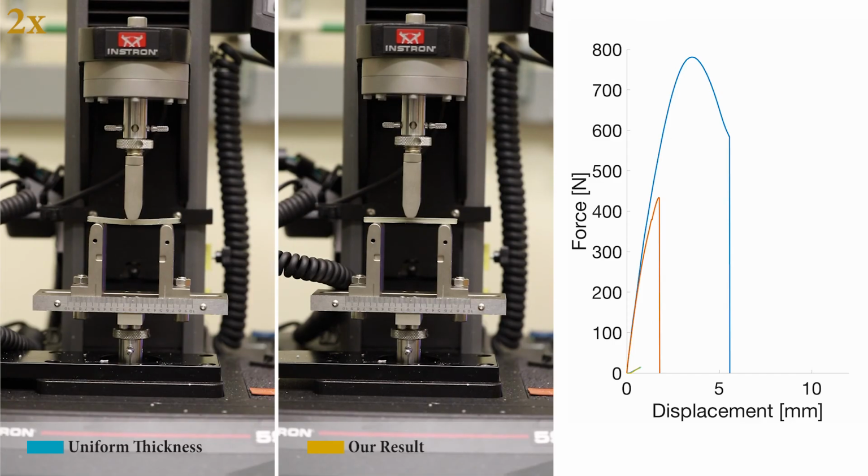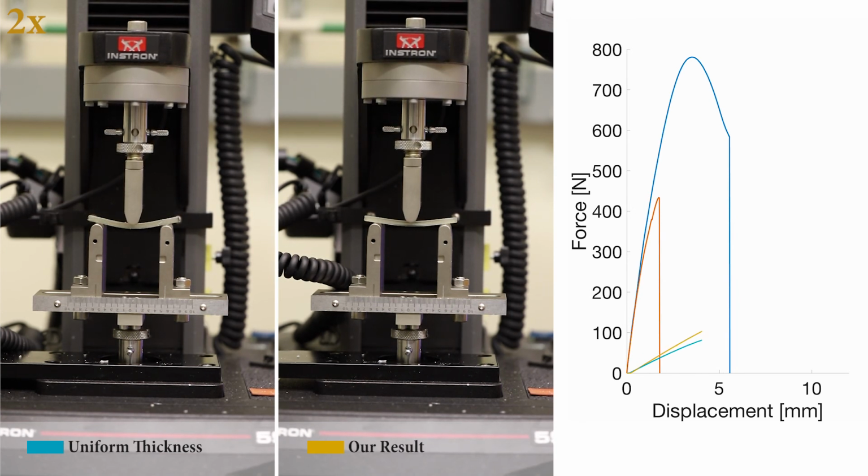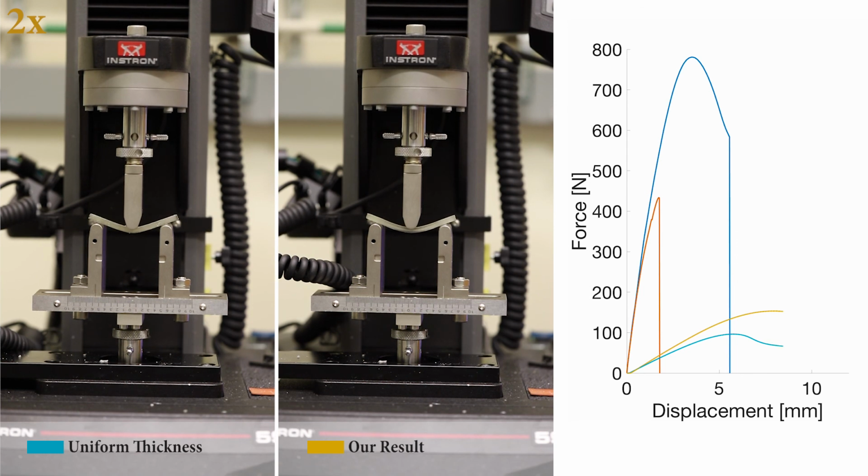However, in 3-point bending tests, the uniform model fails to satisfy the design constraint, while our optimized result can withstand 153 newtons of load. Our method balances tensile and bending performance by moving material toward the center.